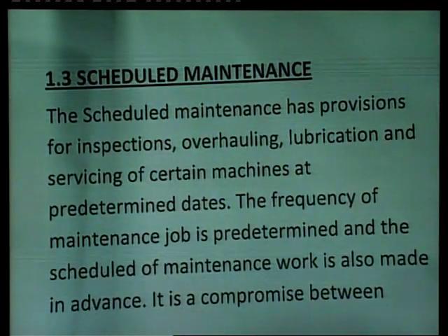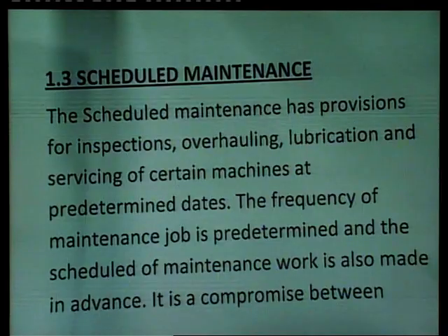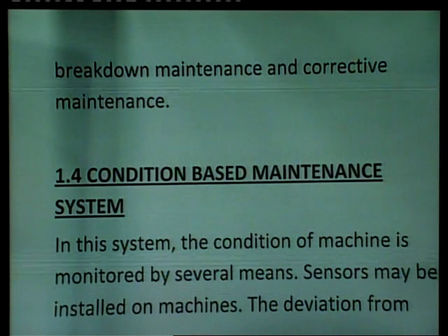Next one is the scheduled maintenance. The scheduled maintenance has provisions for inspections, overhauling, lubrication, and servicing of certain machines at predetermined dates. The frequency of maintenance job is predetermined, and the schedule of maintenance work is also made in advance. It is a compromise between breakdown maintenance and corrective maintenance.